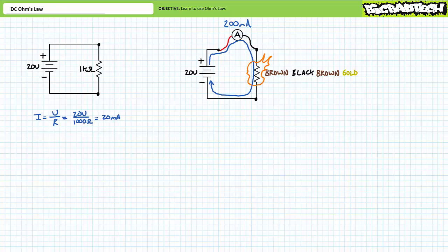900 ohms less, to be exact, than the specified 1 kilo-ohm resistor. The application of Ohm's law demonstrates that the smaller 100 ohm resistor with a 20 volt differential across it should experience 200 milliamperes of current, i.e., 10 times greater than what we anticipated. No wonder it burst into flames. Ohm's law says current will be high for low resistance paths.